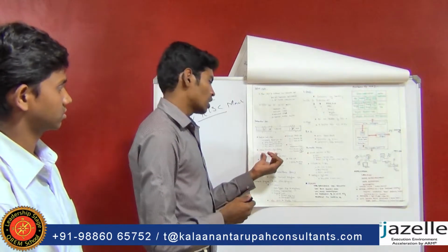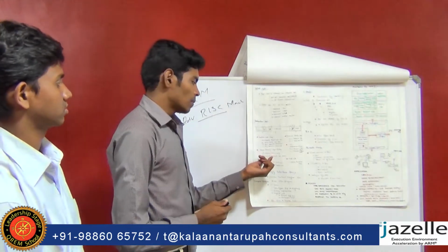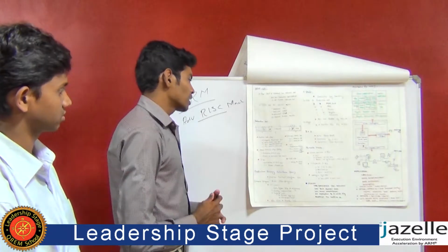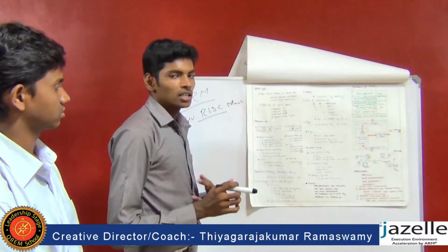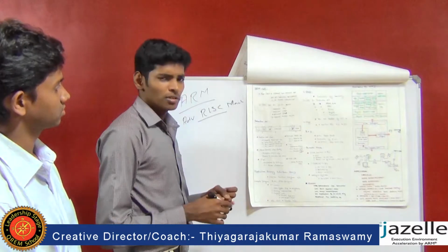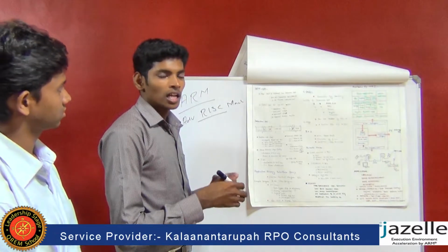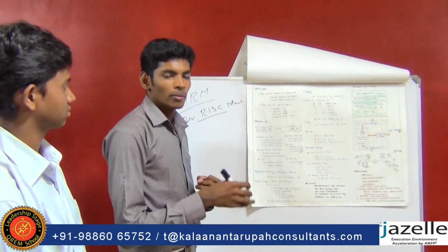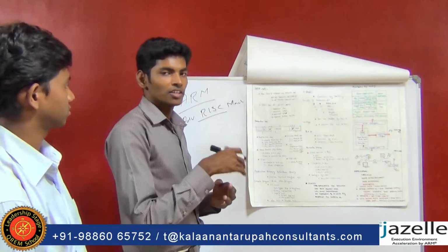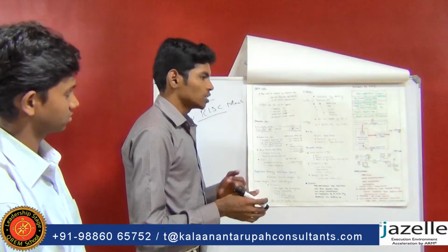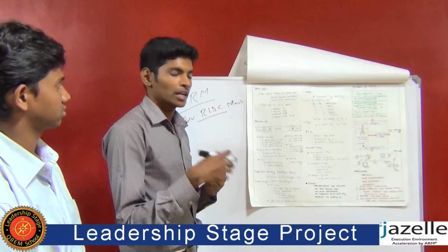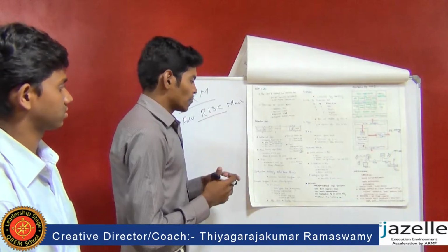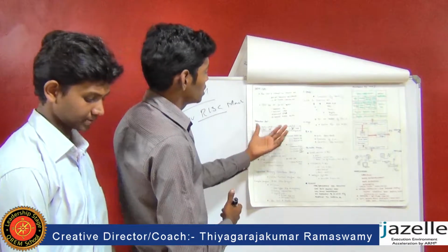Then coming to Q, it is present in architecture V5. It indicates whether saturation has occurred or not. And then coming to the conditional flags, there are 4 conditional flags: N, Z, C, V. If the N flag is 1, the arithmetic operation result is negative. If the Z flag is 1, the arithmetic operation result is 0. If the C flag is 1, the arithmetic operation had a carry. And if the V flag is 1, the arithmetic operation overflowed. So that is about the instruction set.